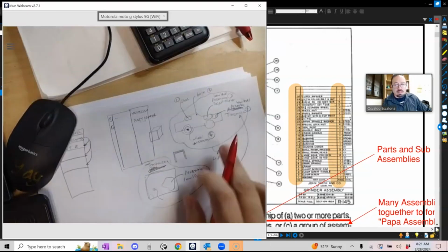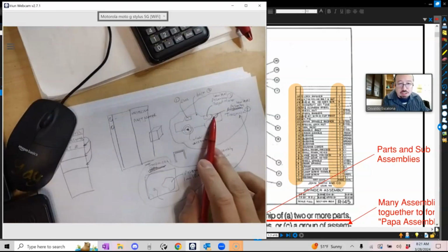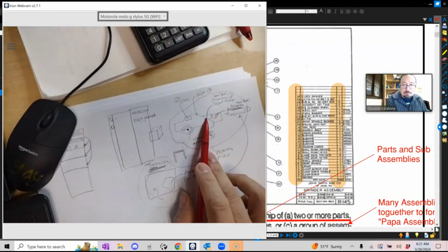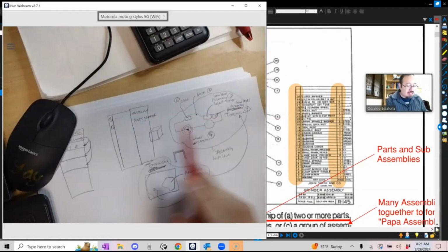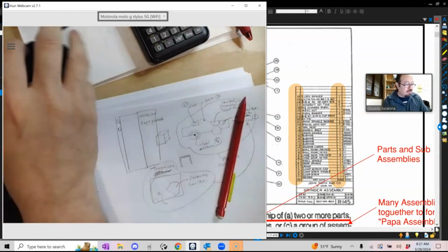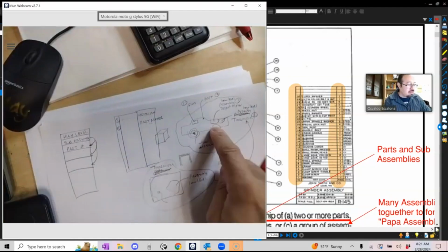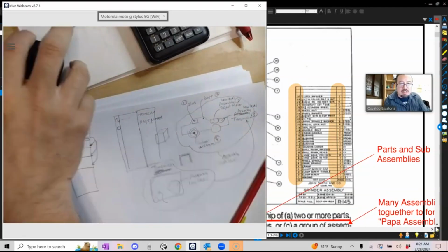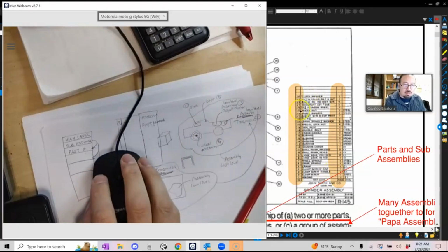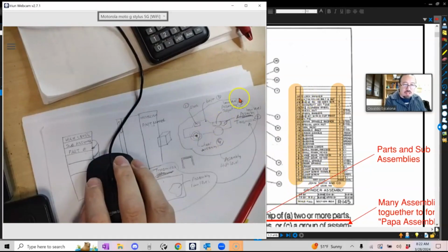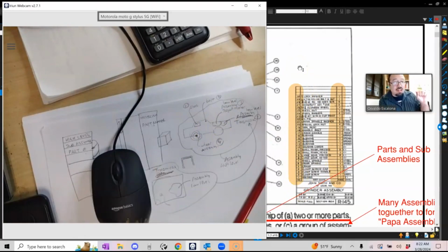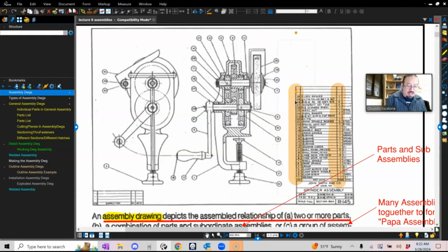Again, remember, a subassembly is the low-level assembly, like your transmission or your motor, something that's a little bit more complex. Otherwise, if you were to put everything in one assembly, just imagine a car, this list that you see there would be infinite. Too many parts, everything all put together. And it would also be super hard to show every single part, because the transmission in itself is a jungle. So you subdivide it. It's called divide and conquer.